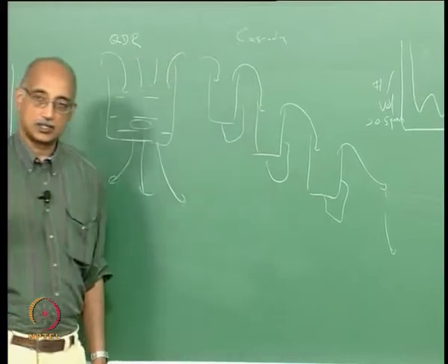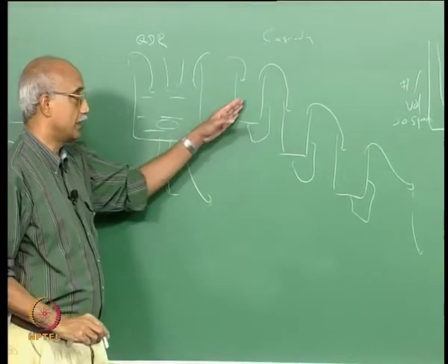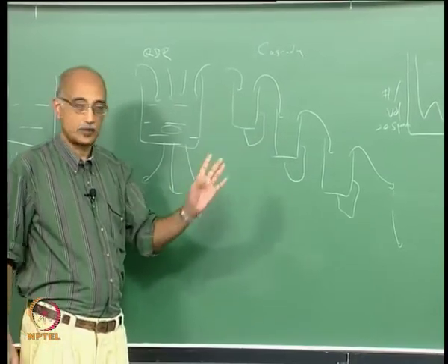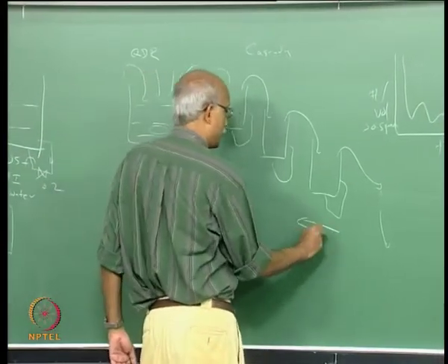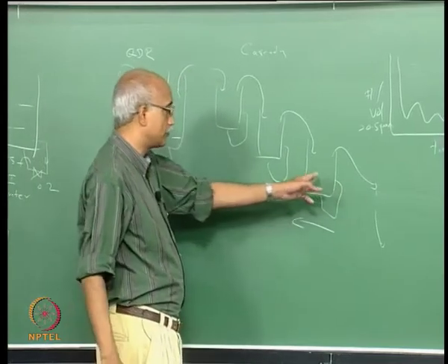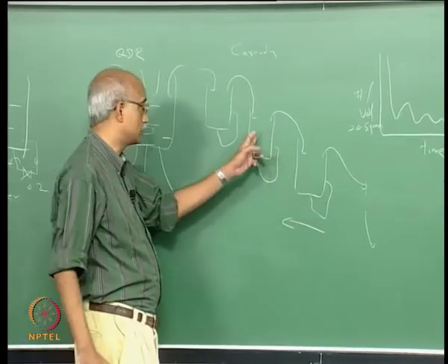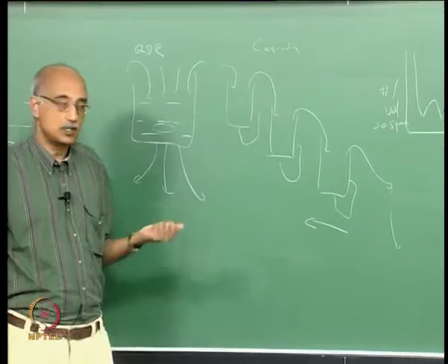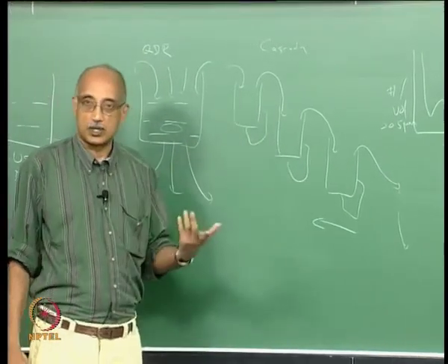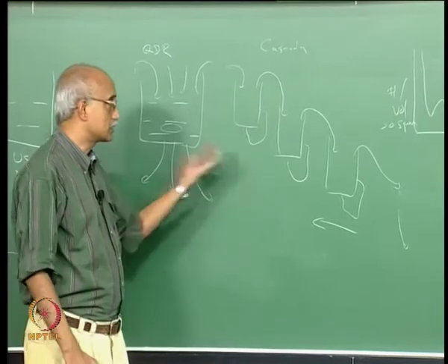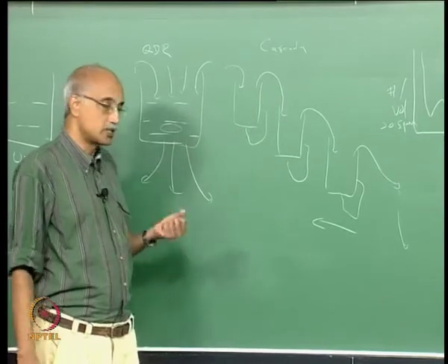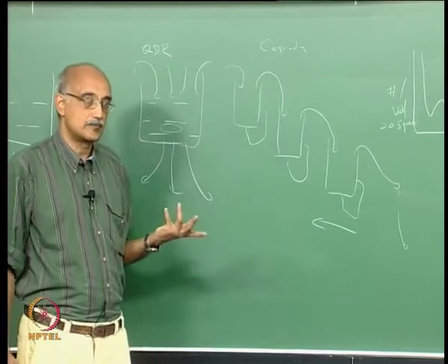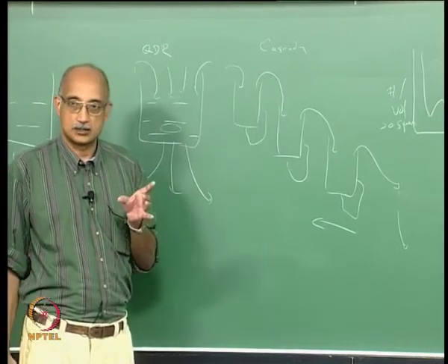In this configuration, the purest water will enter in the first tank, or in a way the last tank, because the process itself will be running this way. So, the wafers will be first taken into this tank, and then into this tank, and then into this tank. The last tank that the wafers see is the one that has the purest water in it. By this type of arrangement, it is possible to minimize consumption of water and at the same time achieve a high degree of cleanliness of the wafer.